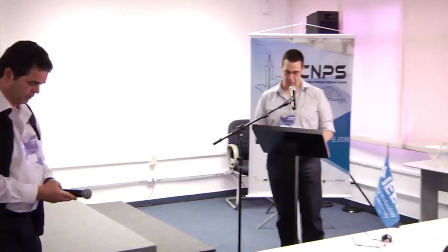Okay, well, great question about the mitigation. There is a typical strategy that is widely employed in grounding system analysis, which is to cover the ground with an insulating material. So if you detect violation to the safety standards, you can use a layer like 10 centimeters thick of crushed rock, for example. It will not change the value of the step voltage itself, but it will create a higher allowable limit because it will isolate the operator.